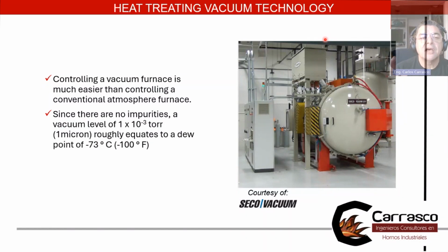But anyhow, I have to read the gases inside the furnace and see what is happening, and then add different gases and control the proportion of those gases and the oxygen present inside the furnace. So I don't carburize my parts. I have to make them brighter, depending on the process I am doing.